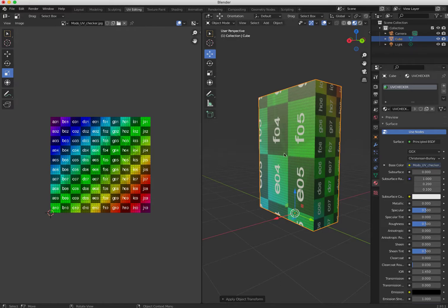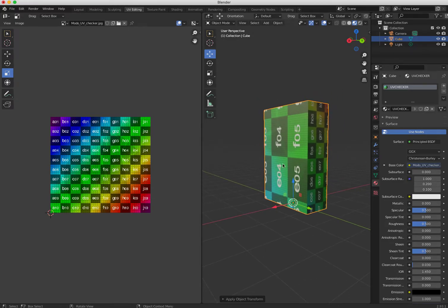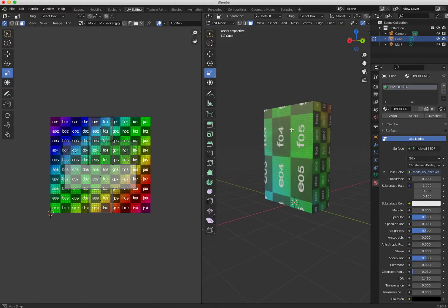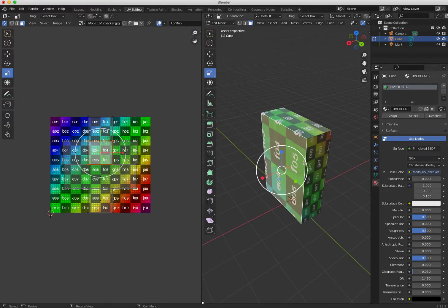I need to tell Blender how to unwrap this, so how I want to apply the textures. So I come to my edit mode and I'm going to create seams. Why I'm going to create the seams, it depends. It's always a bit trial and error. So by choosing the edges, where do you want your object to unfold? Imagine this is a packaging.